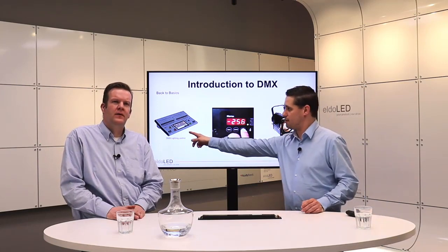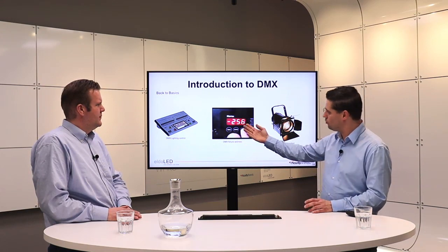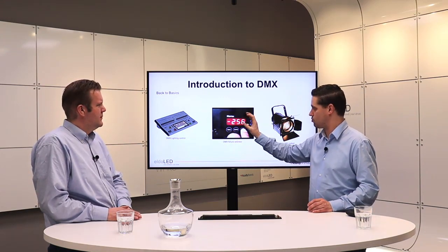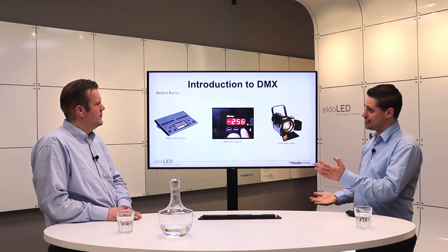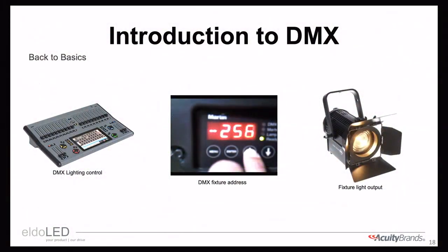That single cable goes from the lighting control desk to the luminaire, and on the luminaire itself, we set the address in such a way that it responds to that particular channel. And the channel is the link to that TV broadcast station. In the end, your luminaire is bringing you the illumination based on that particular channel address, or that dimming value that's been sent out on that particular address.